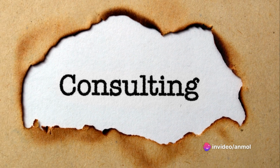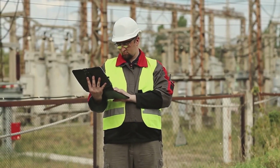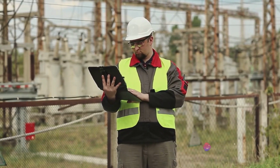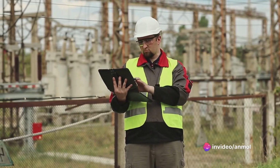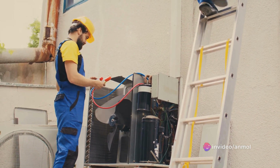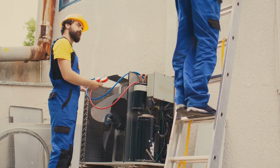Now, while we're talking about rectification, we can't forget about safety. Troubleshooting a VFD is not without its risks. Always ensure the device is powered down and disconnected before starting any work. Wear appropriate protective gear, and if you're unsure about anything, don't hesitate to seek professional help. It's better to be safe than sorry.